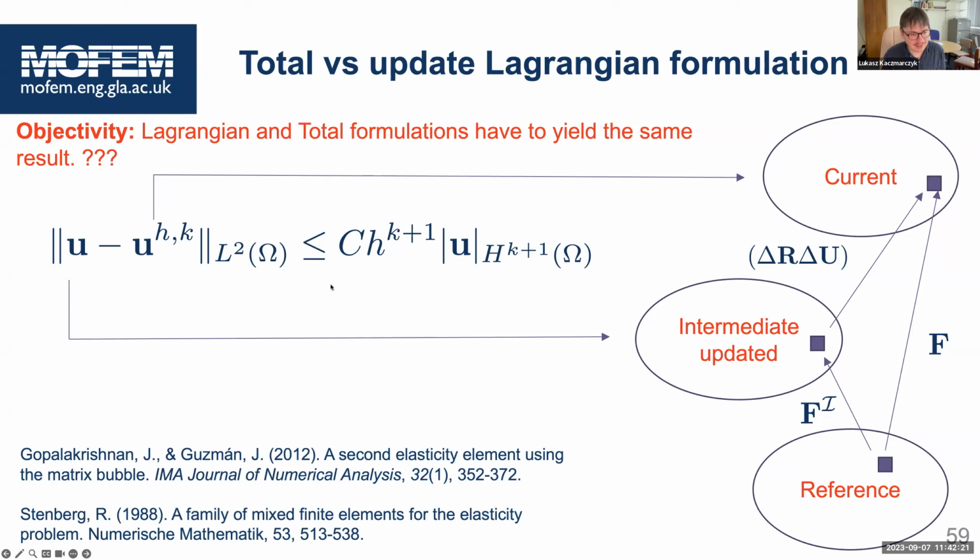So then you have estimation of error for free, which can work in the nonlinear large elasticity case, which is a big problem. But now, because we're using mixed formulation, that problem disappears. So what you can do when you solve your problem using mixed configuration, you have this shadow intermediate configuration which follows you from one step to another or from one iteration to another, and then project constantly the displacements as a post-processing from L2 into the H1 space.